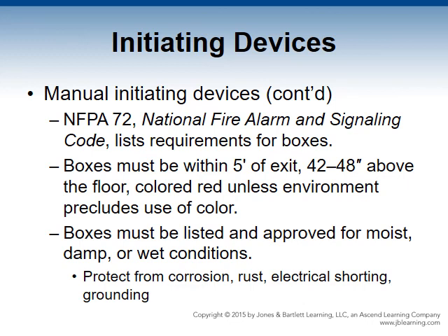They must be located within 5 feet of an exit. They must be mounted between 42 and 48 inches above the floor. One must be located on each side of an exit opening greater than 40 feet wide. And one must be located within every 200 feet of travel distance. If the distance is greater than 200 feet, additional boxes are required.